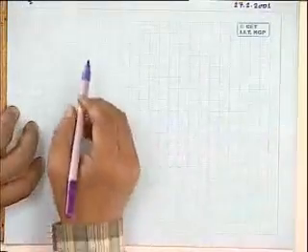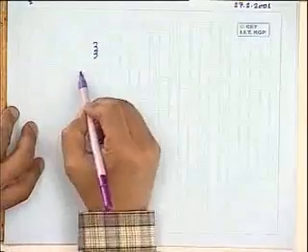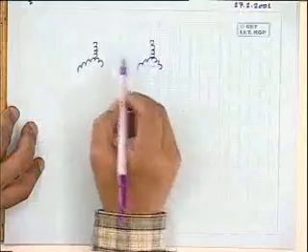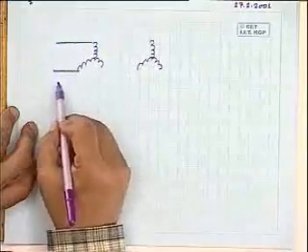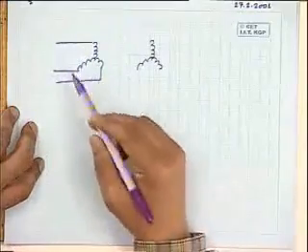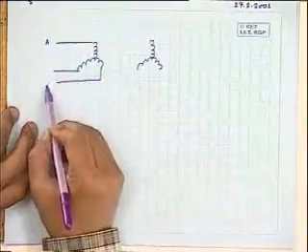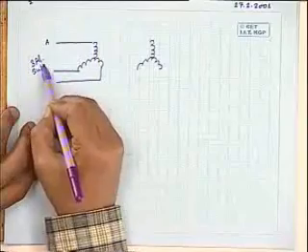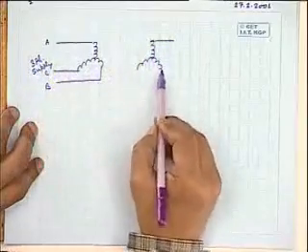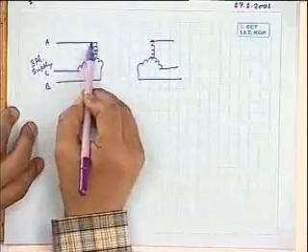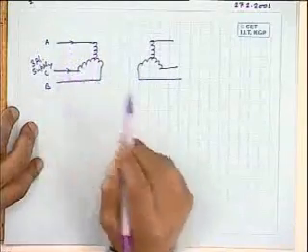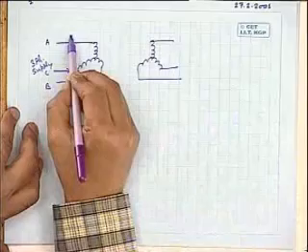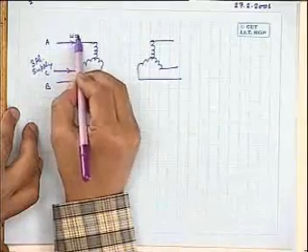and see what happens. This also we discussed briefly. I will just tell you quickly. Suppose you have a star-star connected transformer with neutral not present, only the 3 lines A, B, C are present, and you apply a 3-phase balanced supply here. Then the magnetizing current drawn from the supply cannot contain a third harmonic component. So it will always draw a current of fundamental frequency omega, which is equal to 2 pi f.